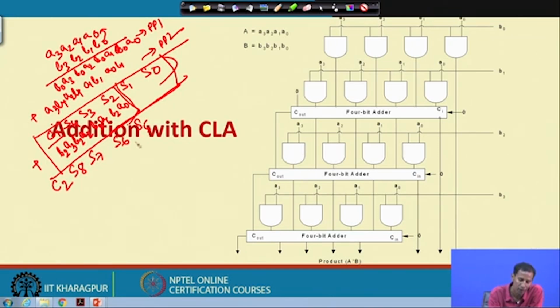Then again along with this, it will start from the 4th position, that means 1, 2, 3, from S6. Then again I have to add A0 B3, A1 B3, A2 B3 and A3 B3. Okay. So, now the S5 computation is already over. Now, after that again I have to do this.